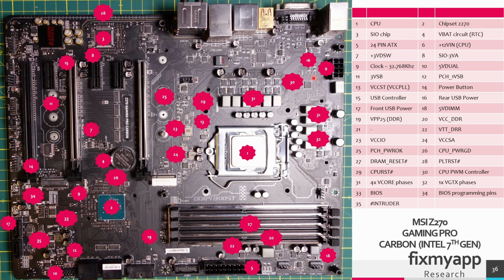In area 30 we can find the CPU PWM controller. This controller will drive the VRMs that will generate the V-core for the CPU and the graphics core for the CPU. In area 33 we can find the BIOS IC, and on 34 we can find the BIOS programming pins. With these pins you can flash the BIOS in circuit without removing the BIOS.